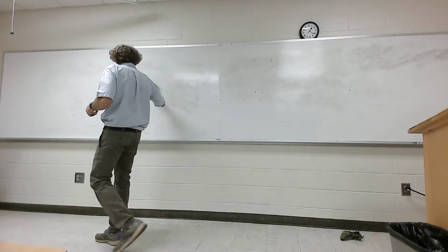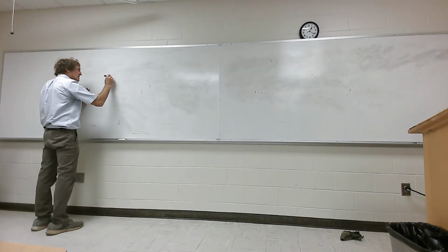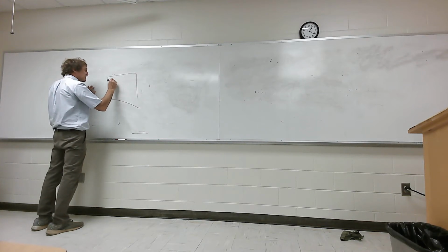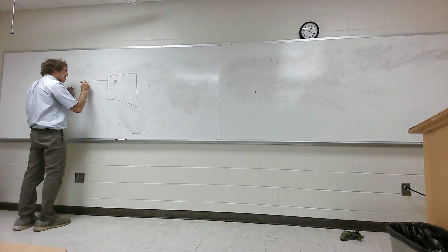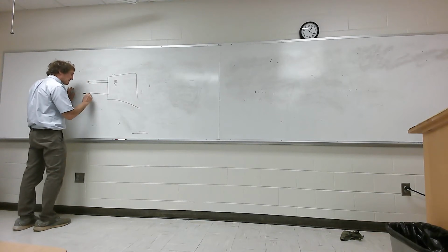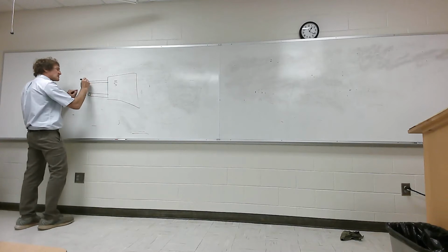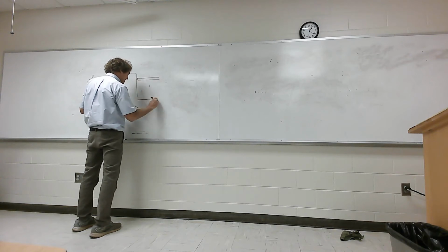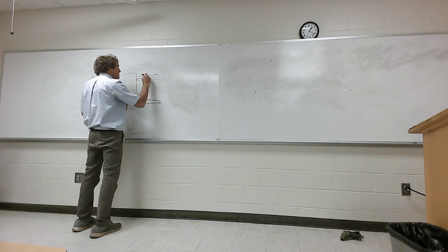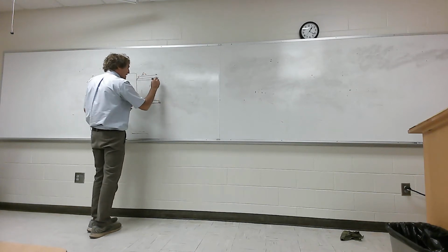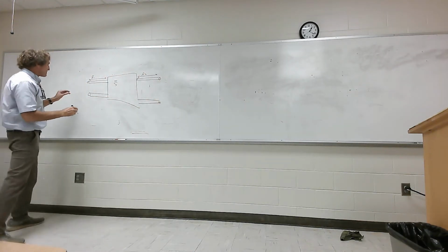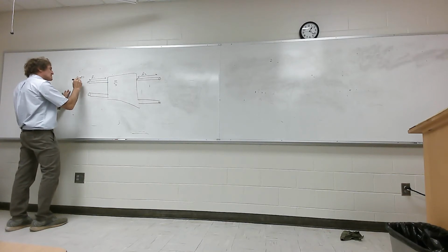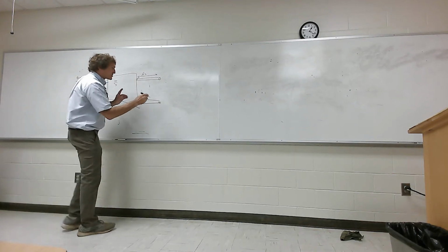And the way it works is like this. If I have my little filter, whatever it is, and S parameters right here, and this is going to be S parameters for that system. But then I say that I'm actually going to be using the device with the length L1 here, and with the length L2 here. And what I want is the S parameters of the new port 1 would be here now. Port 1 is shifted by this much, and port 2 would be here.